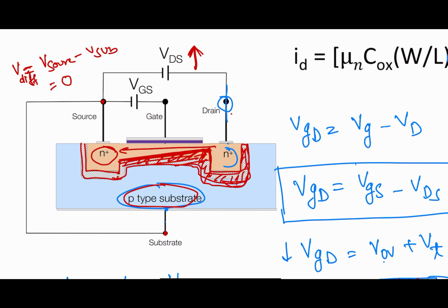Okay, so I think you understand the concept. First, the important thing is you need to understand why the depletion region increases, and why, if we increase the VDS, the current behaves as it does, just like last time I showed you. This is the ID versus VDS. So why, if we increase the VDS, is the current ultimately saturated? But when the VDS is small, you can see it increases linearly. So why is this happening? This is the main reason.